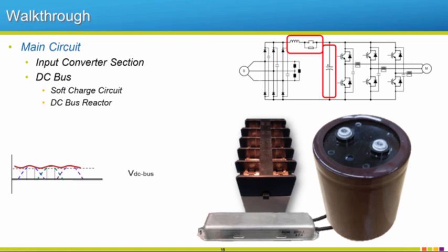Then we move to our DC bus. So we've got the top part of that waveform that we chopped in half with our diodes. And since we have this capacitor here, we're actually going to start to fill in these voids, so it's going to smooth out this DC bus ripple, which is very bad for a drive. So things that would cause excessive DC bus ripple would be like if you would try to single phase a drive. You can do it, you just have to deal with a big derate, so that would cause excessive DC bus ripple. But if we have three-phase incoming, you have that 120 degrees evenly distributed waveform going across here for all three phases, so it smooths out that DC bus quite a bit with the help of this capacitor.